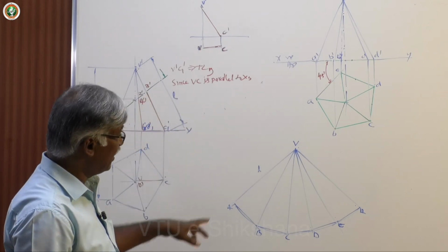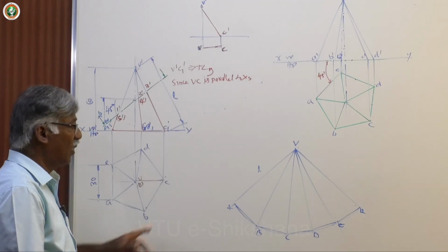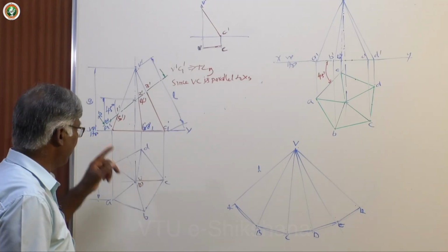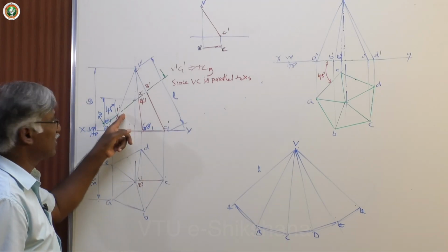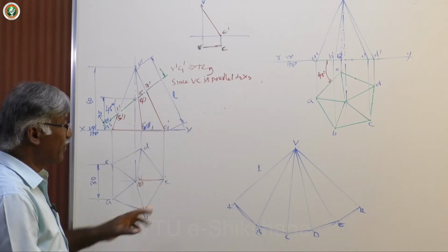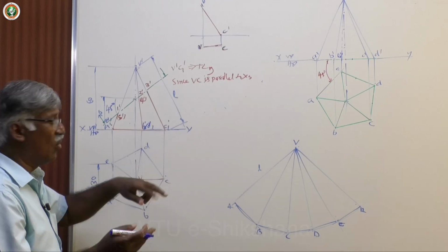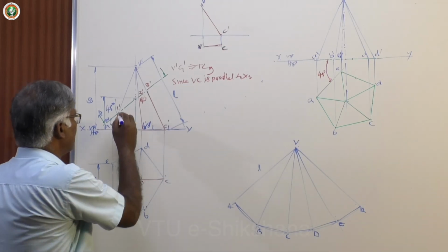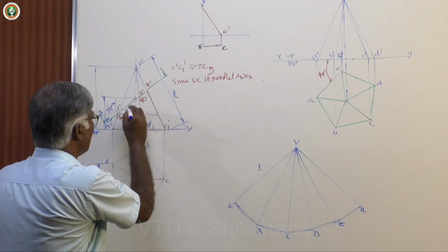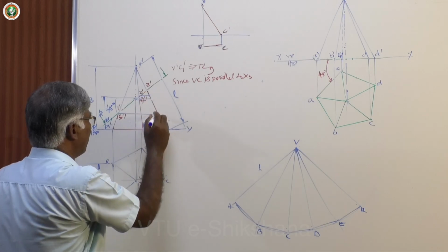Next comes the points of intersection we have located. How to get these points of intersection? We must project all these points onto true length line. In some cases, none of these lines may be true length, so you will get extra line, that you know, already we worked out some problems. Now, this one you project, this one you project. In case of cone also same thing.